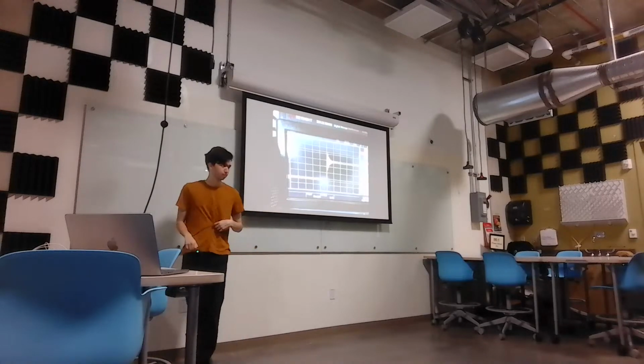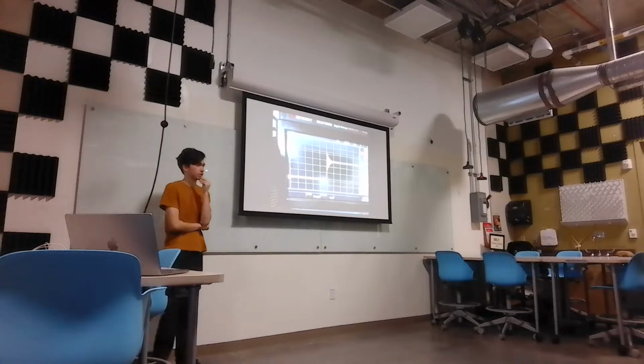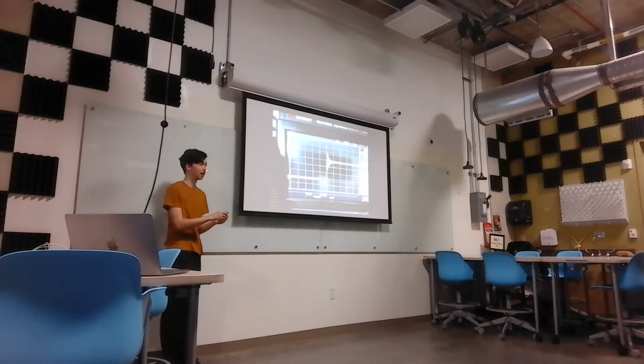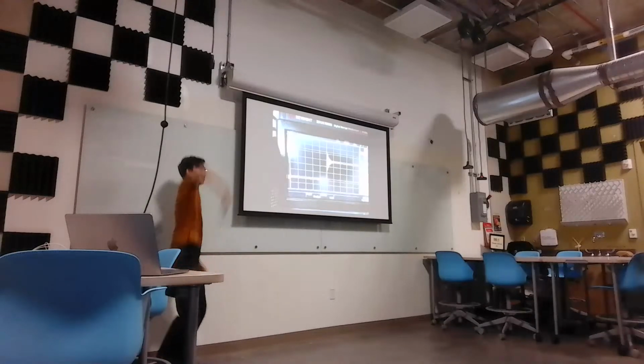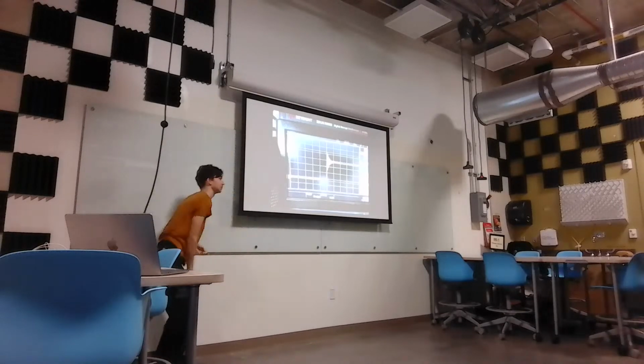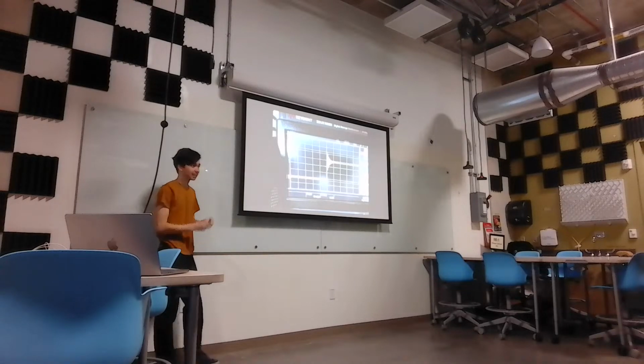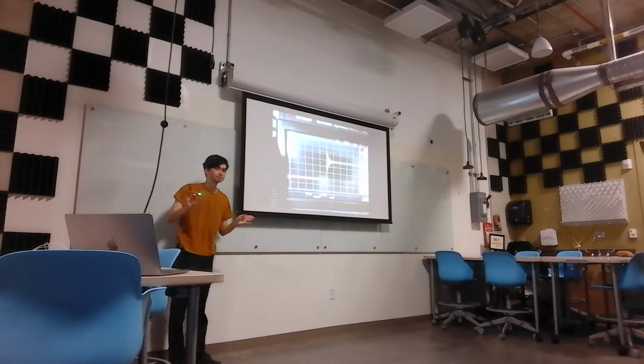You mean a low pass filter at the high frequency? So you're saying snubber. That's what everyone on the internet said. That is absolutely not what you should do. The snubber gets so hot because it is on the output. So it's going 84 volts, 0 volts, 84 volts, 300,000 times a second, that capacitor explodes. That's not the solution. We shouldn't need that.